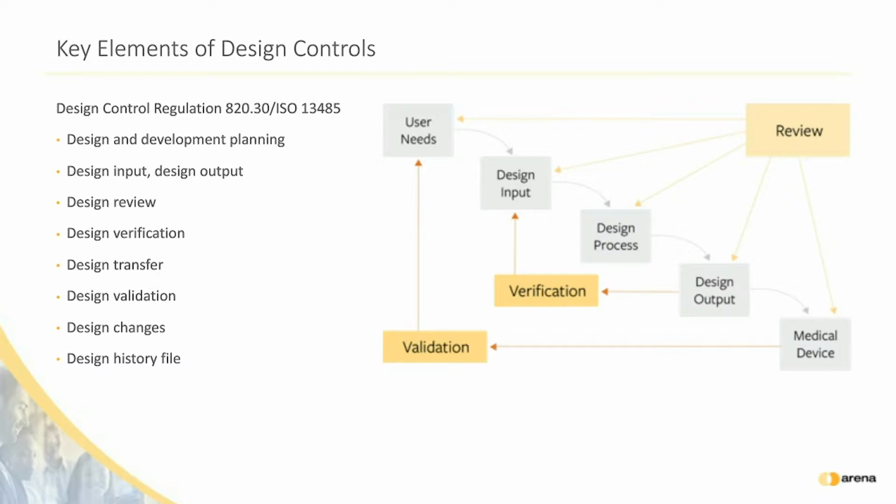Verification means making sure that the design outputs completely and unambiguously match the design inputs. In verification, you should be able to answer questions like, do we have all the documentation we need? Who's approved it and when? What's missing? Design transfer is the process of providing manufacturing with the information they need. Design transfer is worth noting today, even if it's not as frequently cited in the 483s, because in our experience, we so often meet companies where the transfer of information from engineering to operations is manual, risking delays and errors.